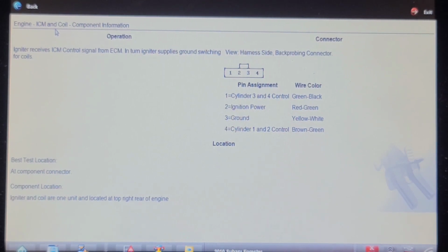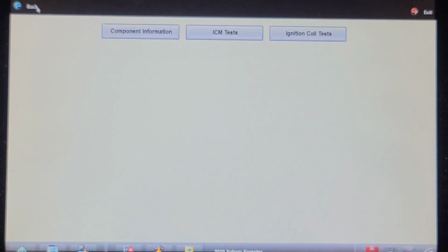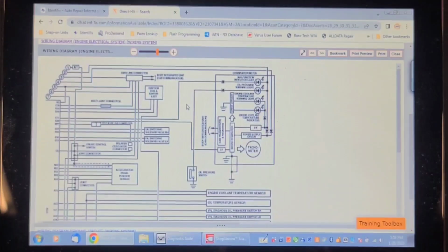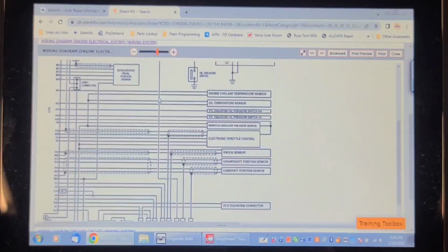This is showing that it's got transistors in the coils, in the coil pack. I'm going to look some more. So here's an OEM diagram, and it shows the ignition coil igniter assembly with 4 wires to it. And usually when it says igniter assembly, it contains transistors. But I'm not completely convinced.